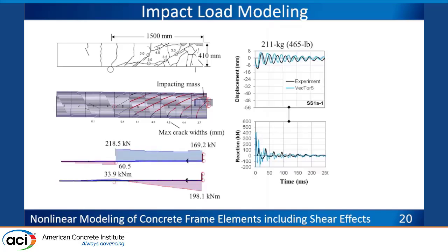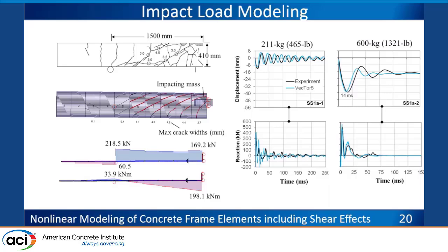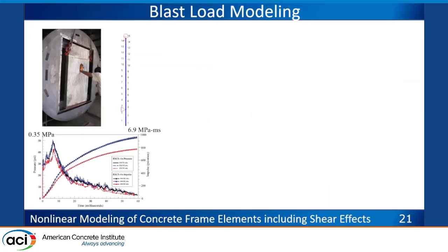For the sake of time, and also you can get the moment shear diagrams. Practitioners really like it, because in a continuum model, what you get is stress contours. Some practitioners have trouble using it for design purposes. So you can see this is the maximum moment, this is the maximum shear. You can see this is the dynamic response: time history, displacement, peak, reaction.